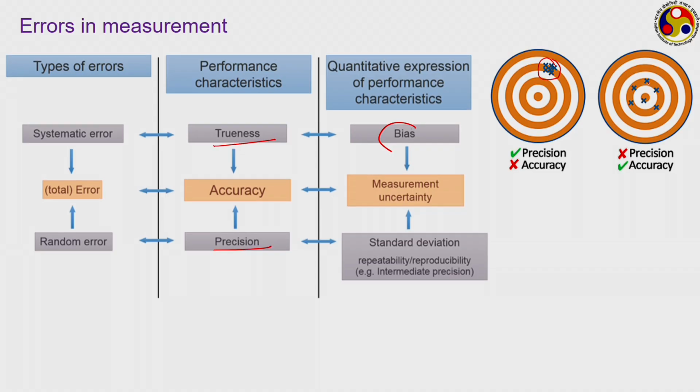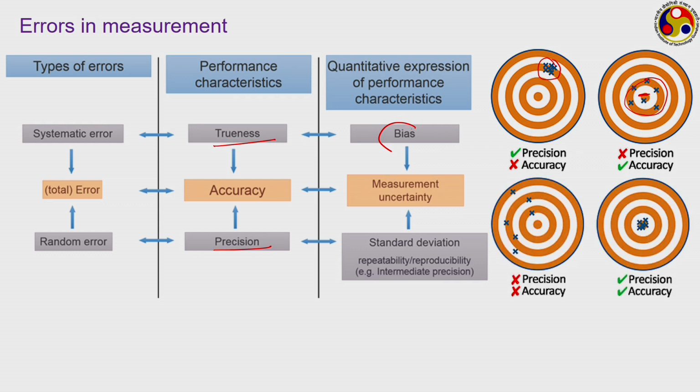Similarly, when the system is not having any kind of systematic error, that is a highly true output that we are getting, but random errors are present, then we may find that all the observations are well scattered, generally around some kind of mean, which may be somewhere here in this particular example. Both the errors can be present simultaneously in a system, and that is generally the most practical case.